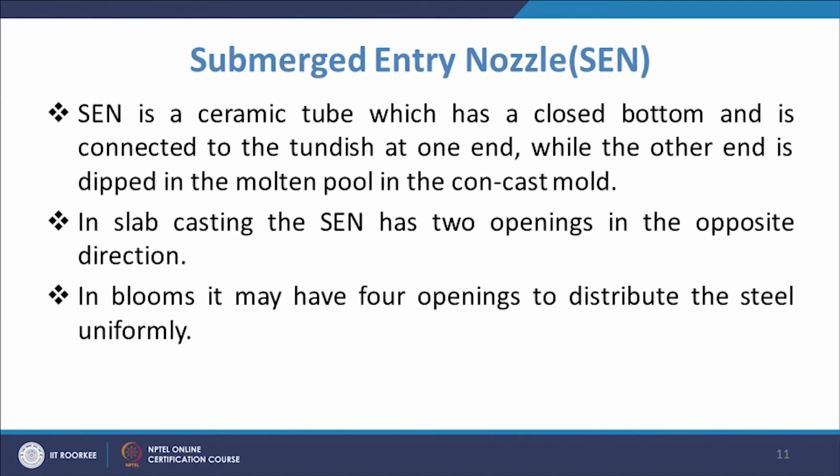In slab casting, this SEN has two openings in opposite directions, and in blooms it may have 4 openings to distribute the steel uniformly.